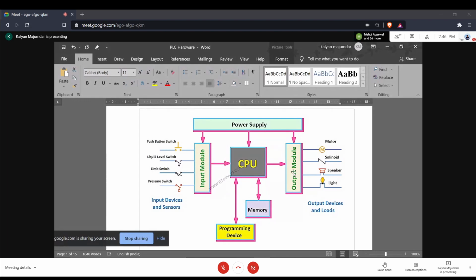You have a laptop which runs a CodeSys-like environment, which is a development environment. It could be CodeSys, it could be Siemens TIA Portal, it could be RSView from Allen Bradley. They're all similar. That is when you write a code. After that, you compile it. Here you say you build, and after that you go online. Online basically means downloading a compiled program into the memory of the PLC, which will ultimately execute this program. So for this entire exercise, you need a programming device.